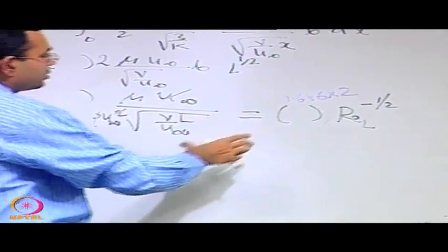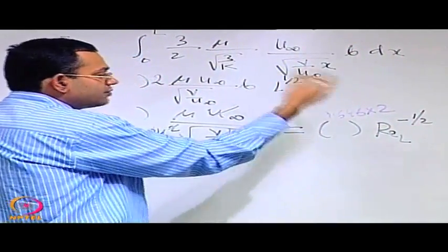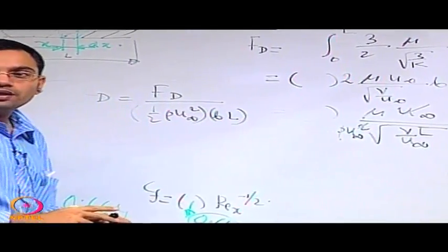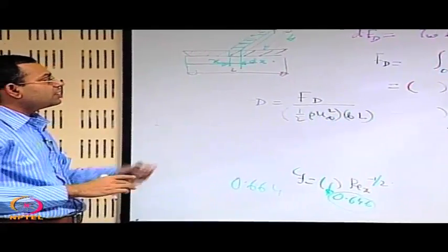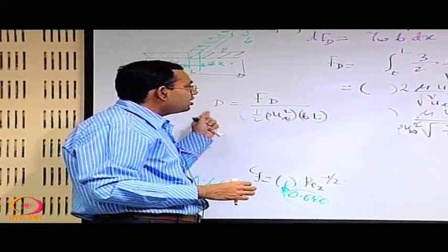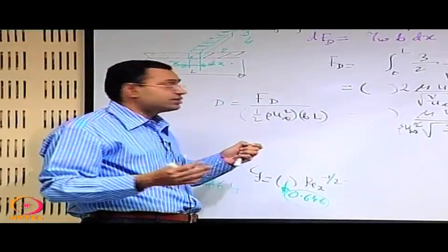It is therefore also quite close to the result that one gets from the exact solution or the Blasius solution. So what we get out of this exercise is that, by using an approximate velocity profile, we may estimate how the boundary layer thickness grows with x, how we calculate the wall shear stress, and how we calculate the total drag force and their non-dimensional versions.